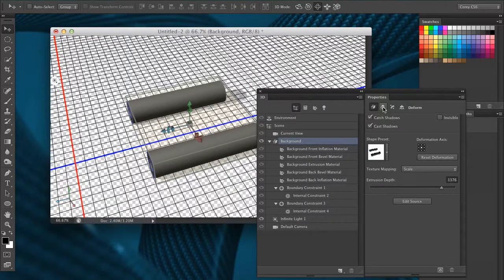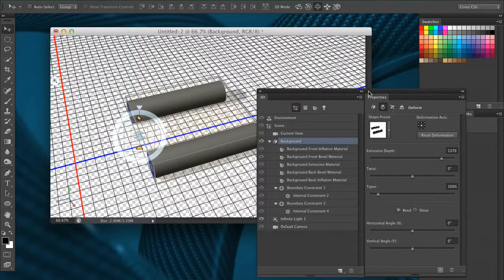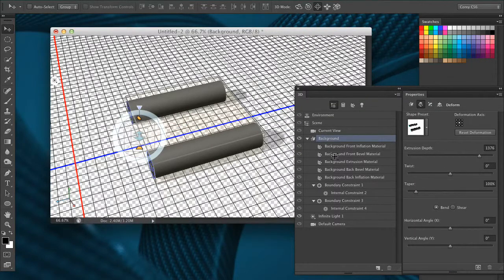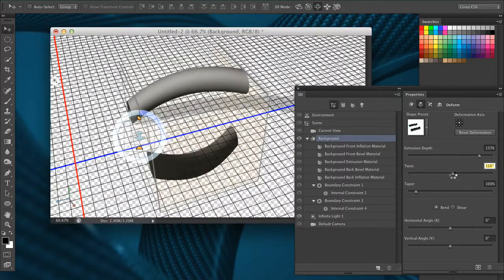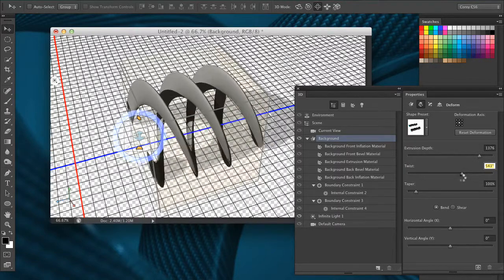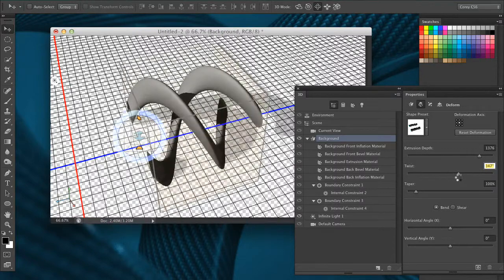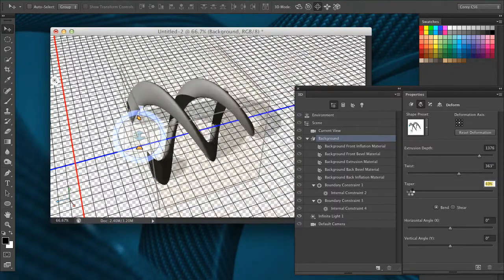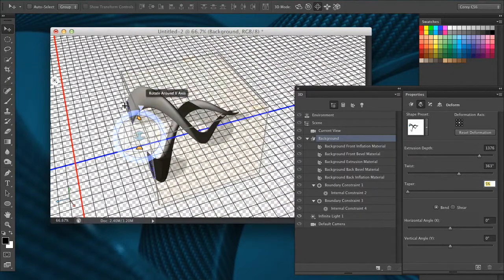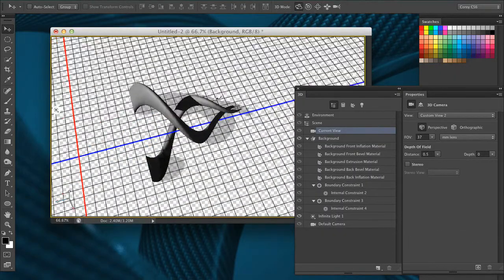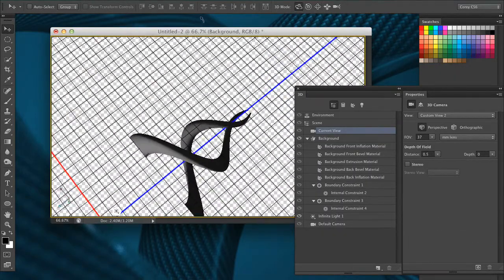And over here, I'm going to go into these properties panels, these tabs up front. If I click on the second one, which is the Deform tab, I can do things like twisting the object. If I move the twist slider, you can see that it starts to twist around itself, giving me a kind of a cool spiral effect. I can have it tapering down or up as it gets closer. And notice the interesting result this gives me with that object.